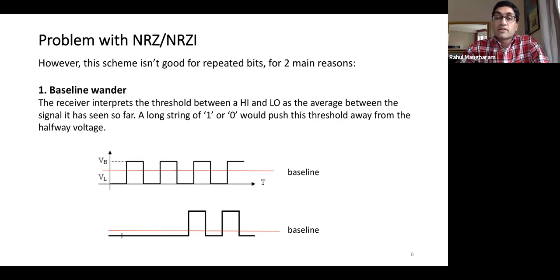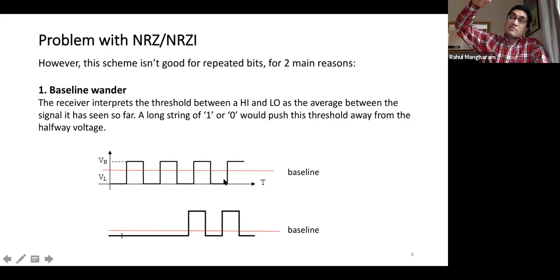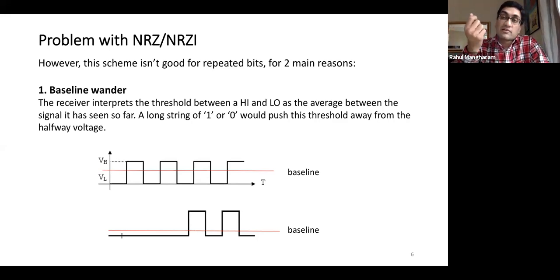But in reality, we're not going to get a clean 0 or a clean 1 on the line, because the line itself sometimes is not going to go all the way down to 0, and it's not going to go all the way up because the line is lossy. And so that's the issue over here, right? Again, we are trying to get timing, and we're trying to get a good discrimination of high and low from the same signal.